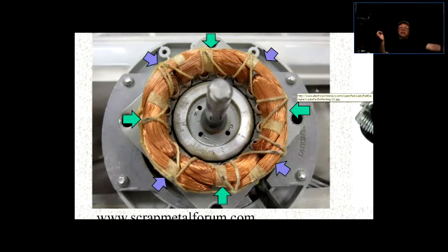And we only need to apply the power for the auxiliary windings at the start, just to make it start. Then once things are in motion, the single phase can just work as it is, because the motion is already happening.